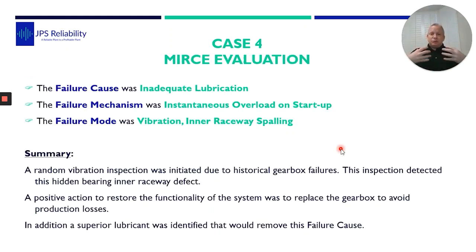So when we took a step back and looked at it, I also have some other experience with these gearboxes. What happens is, when they shut down for the weekends or for maintenance, the oil obviously goes to the bottom of the gearbox. Now the gearbox is at 45 degrees, so a little corner bit of the gearbox has the oil. It has the right amount of oil and the correct lubricant spec from the OEM.